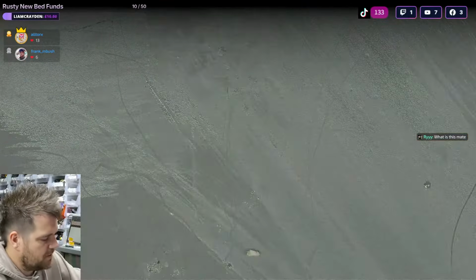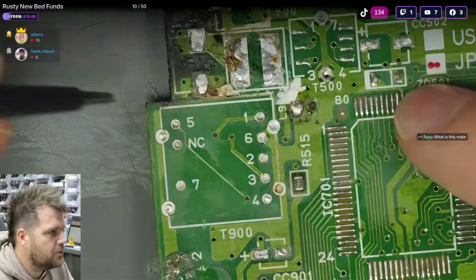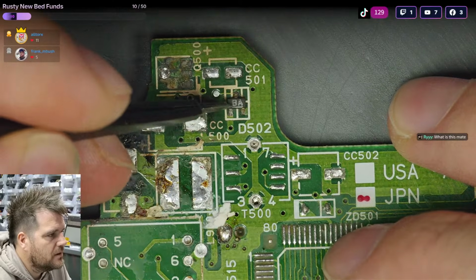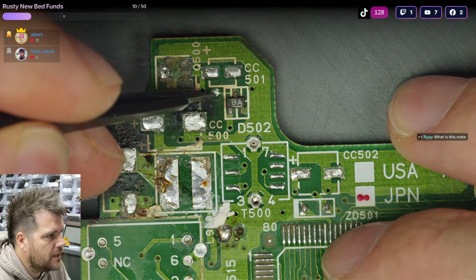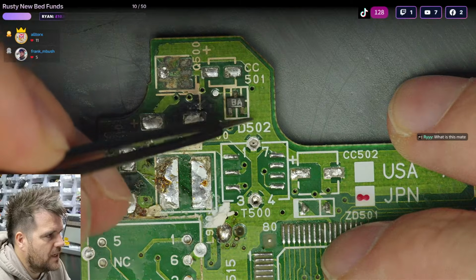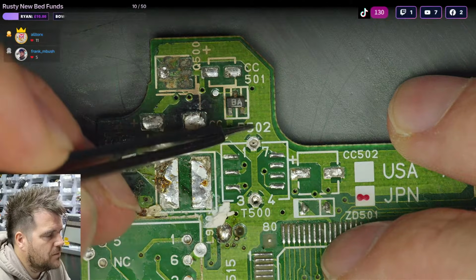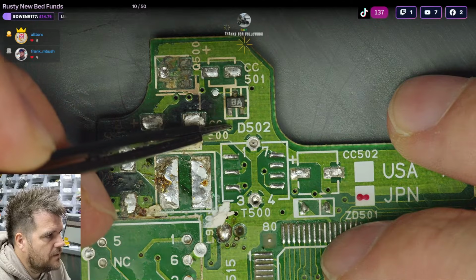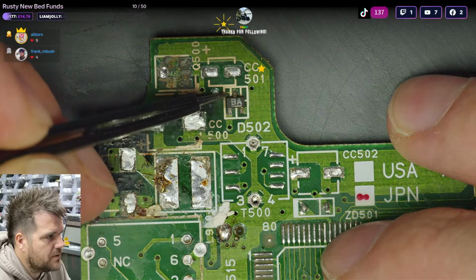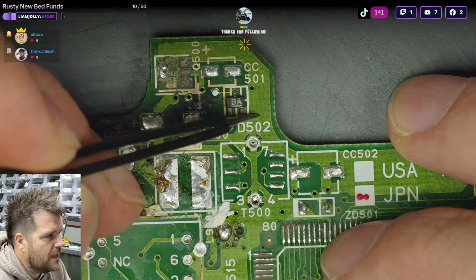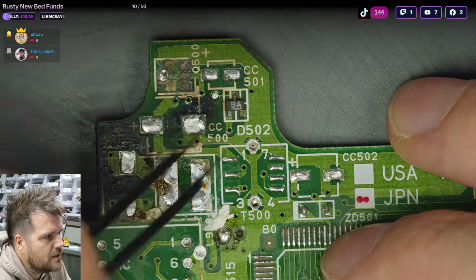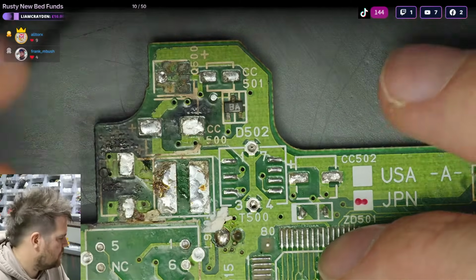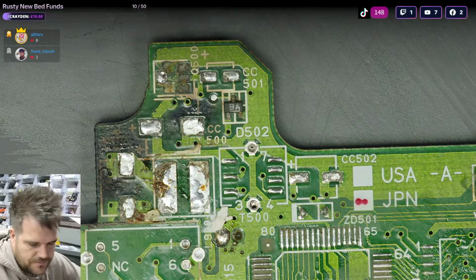So I'm guessing this is potentially a dual diode in a package, so there might be, this will look like, see, it looks like a transistor to me. It looks like it's going to ground here, which would normally be the base. This would be the base with the thin wire. This would be the collector to ground, and this would be the emitter. So to me, this looks like a transistor. This looks like an NPN transistor.